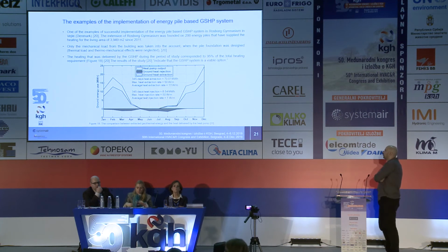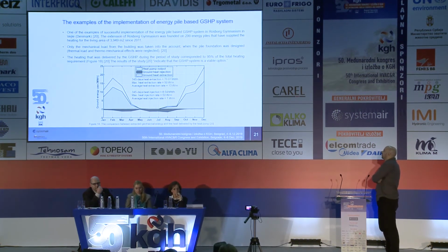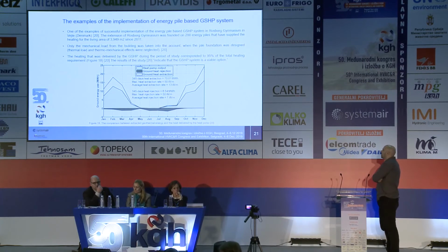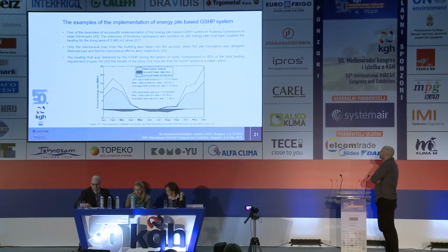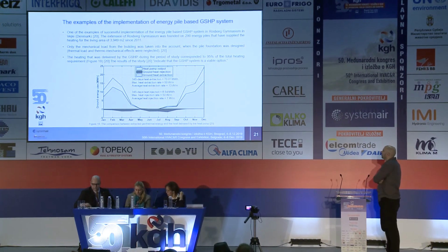There are a lot of examples of implementation of energy pile-based GSHP systems, and I chose two. Basically, one of them is the example of implementation in Rosborg Gymnasium in Denmark. It was the extension of Rosborg Gymnasium, and it was founded on 200 energy piles that have supplied the heating to the living area of almost 4,000 square meters since 2011.